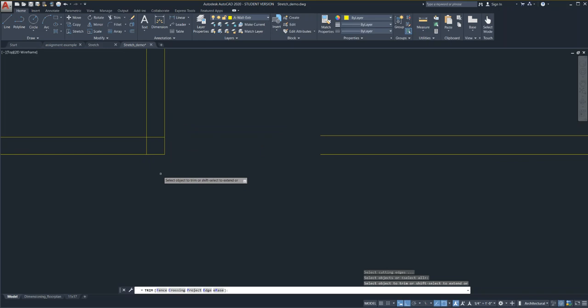So I do have the ability, we'll say ability, to accidentally trim things that I shouldn't have with this command. So you just really have to pay attention to what you're doing when you're using it. Just make sure that you hover over the correct thing. Let AutoCAD sense a good boundary. In this case, trimming off this little line, AutoCAD is automatically sensing this longer line here as the cutting edge, so it's going to be trimmed off at that line. Click, click, and trim works really well. Escape. I'm going to undo again.